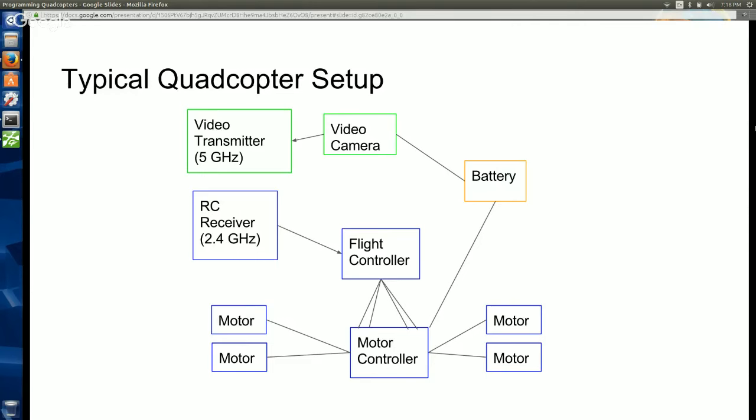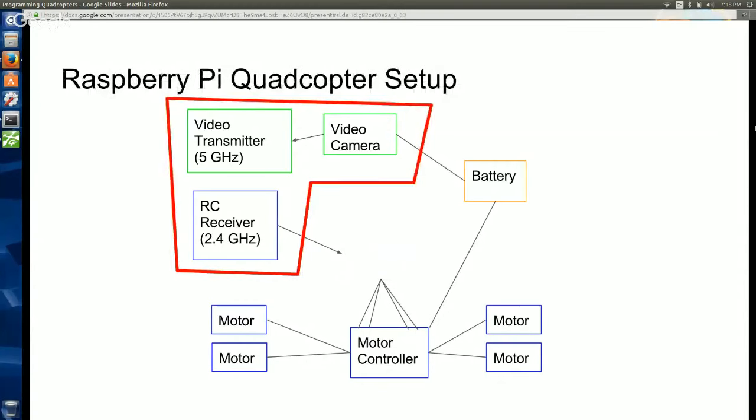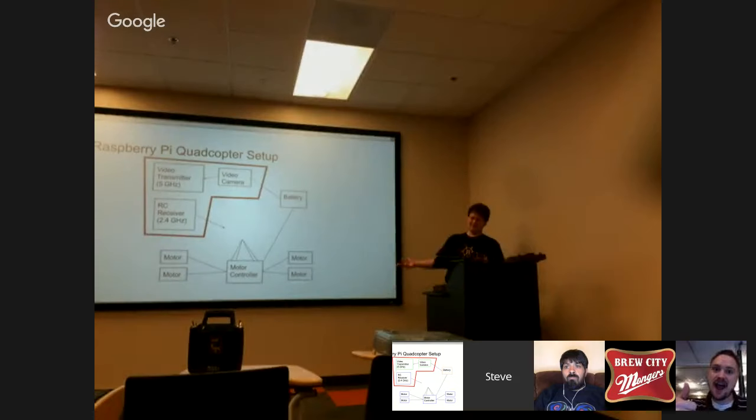And it has to be constantly making those very tiny adjustments to keep it stable. It's not inherently stable that way. So the flight controller is what enables you to do that. The velocity you're controlling? What are you controlling? You're giving it instructions of, I want to yaw, pitch, and roll, and thrust, and then it works out what that means. But the motors themselves, all you really have is how fast they're going, right? Not even that. The flight controller takes care of all that. Right. Okay. Yeah.